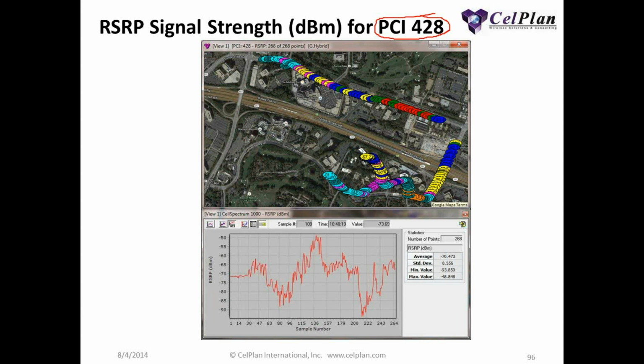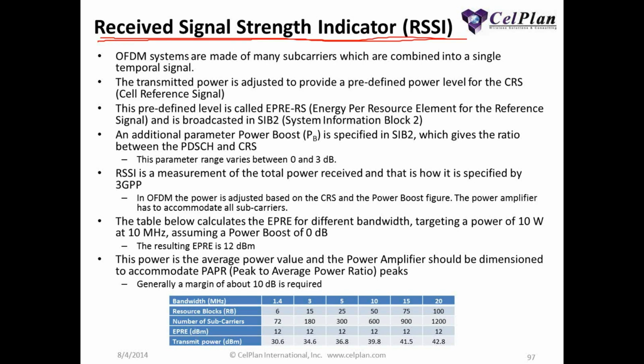The next measurement is one that you are probably familiar with, the Received Signal Strength Indicator, RSSI. But for an OFDM system, this measurement takes a totally different connotation, and it's much more complex because not all subcarriers are transmitting all the time. The transmission depends on traffic, and that changes the power level transmitted. So we need to understand first how in LTE the power level is adjusted.